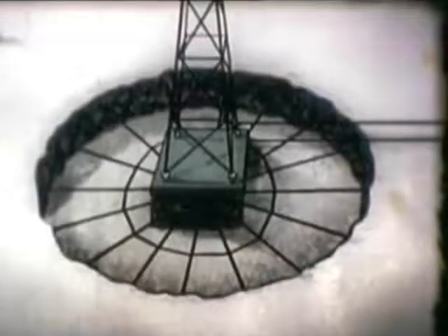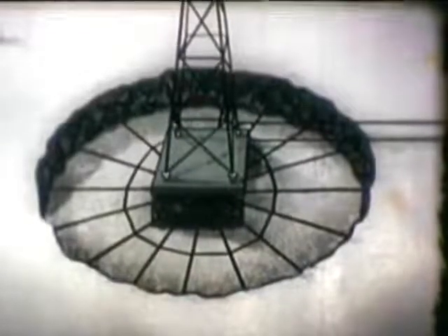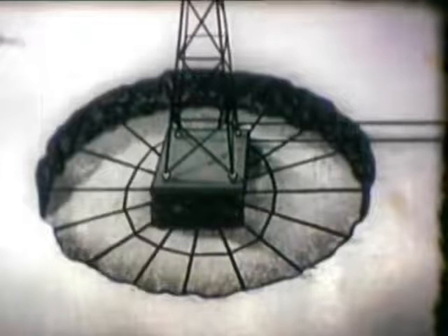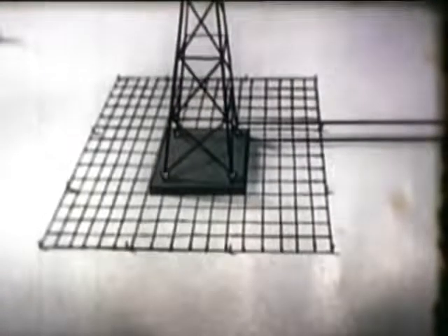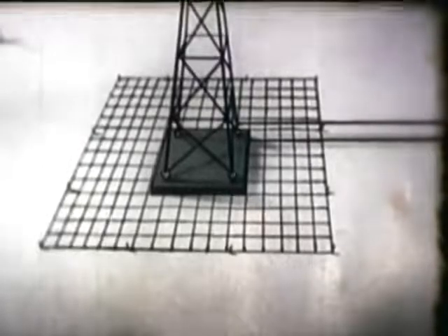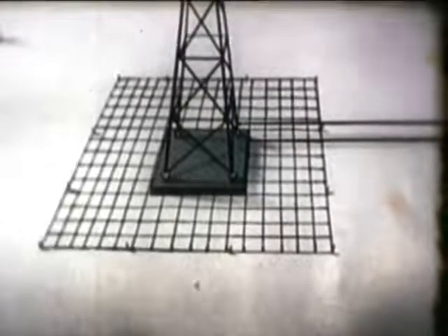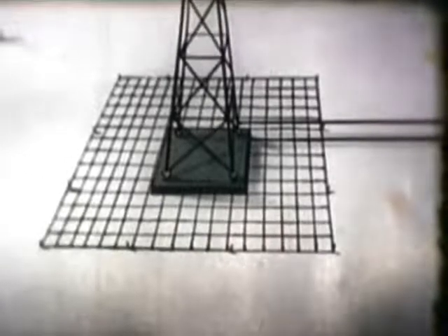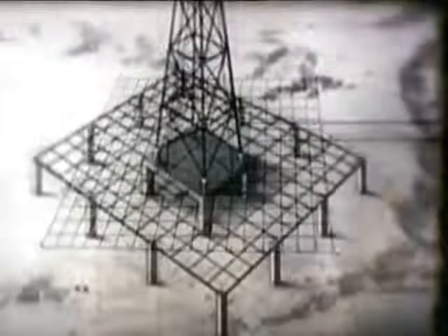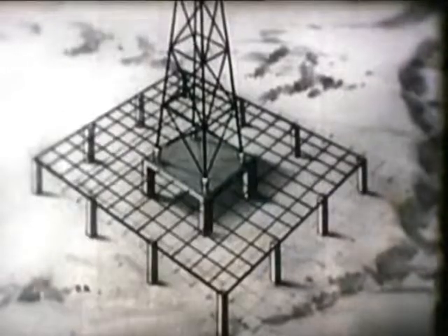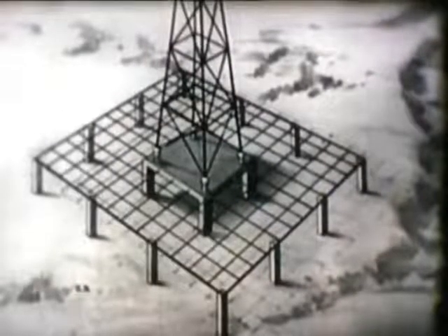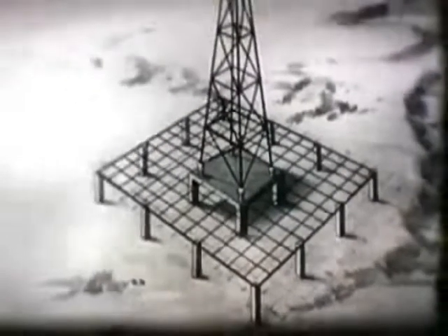In drier regions, a system of conductors installed at the base of the tower may be required. These radial conductors are connected to a common point at the base of the tower. Sometimes on some installations, an additional system of wires lying on the ground called a ground screen is used, thus forming a more effective ground. Where it is not practical to bury conductors, a network of wires called a counterpoise is built above and insulated from the ground.